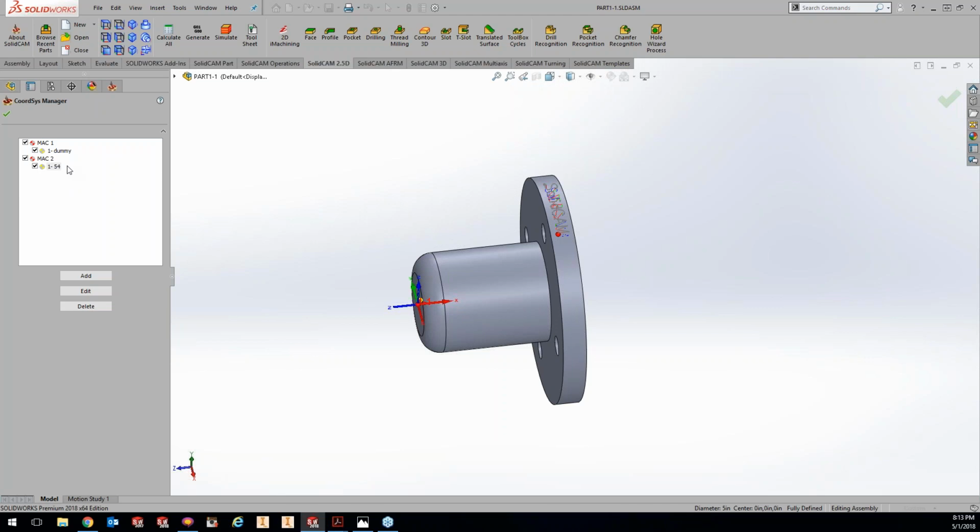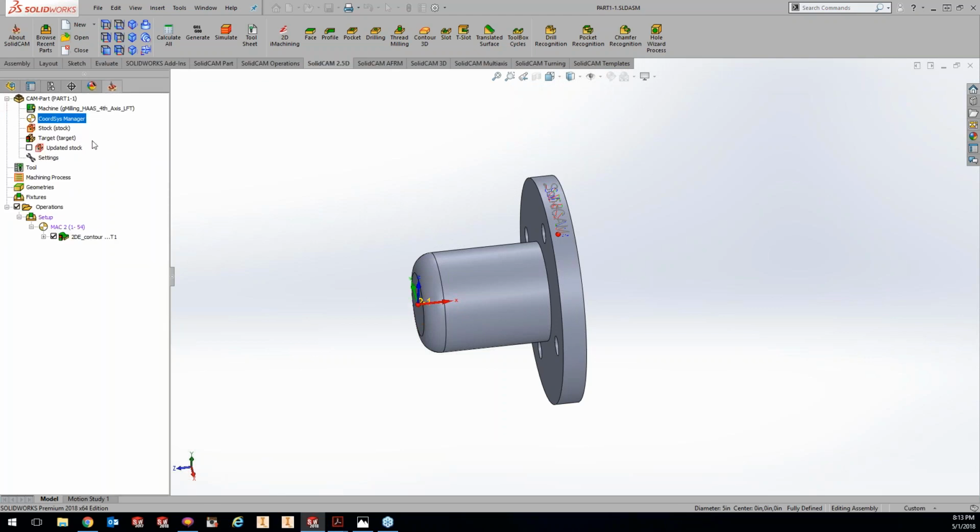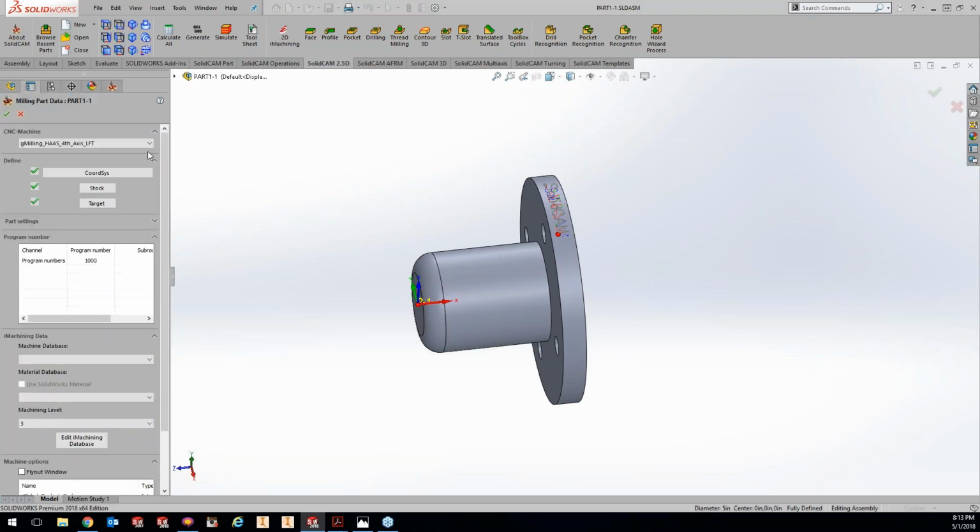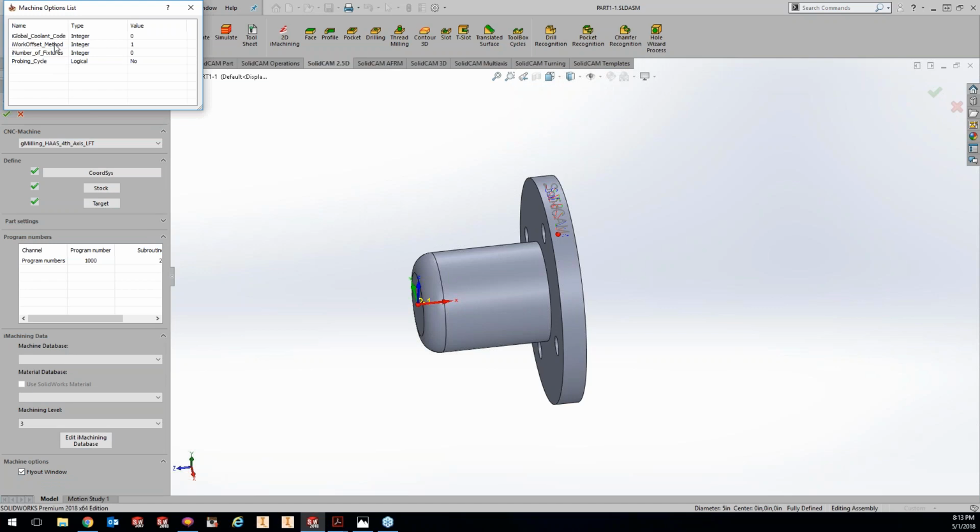Yeah, and Ronnie's saying that's post-related. Yes. So like I said, if you guys don't have this option down here, do the fly out in here to do the I work offset method, let your post writer know, and they can add this in there for you guys. So this is like Ronnie's saying, it's dependent off of the post processor itself.